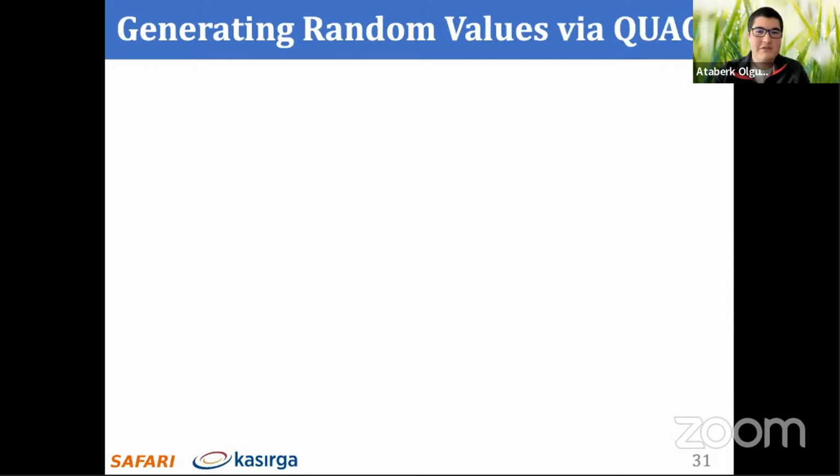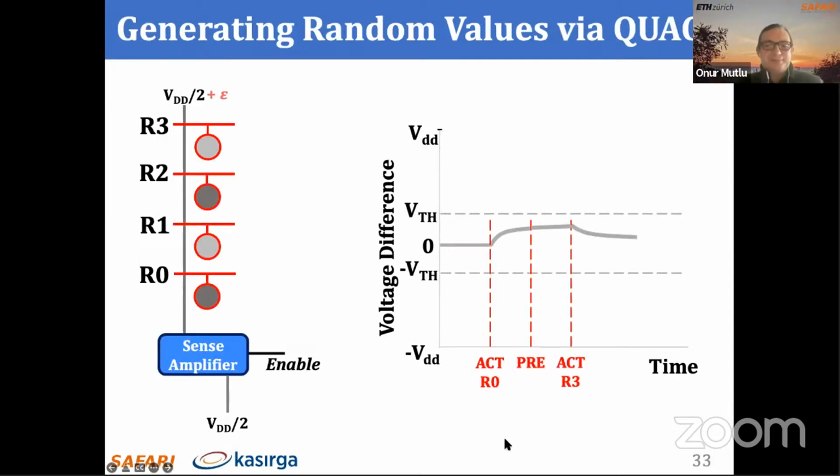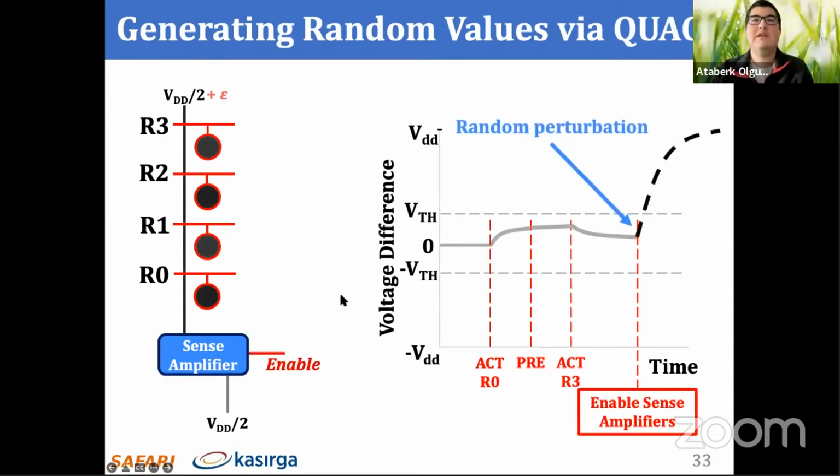So this figure, or this one. So this is our hypothesis. Basically, we think that random values occur when the bit line voltage is below the reliable sensing threshold depicted in this figure as VTH. There is, let's say, prior work that backs this hypothesis up, and you can find more details on that in the paper.